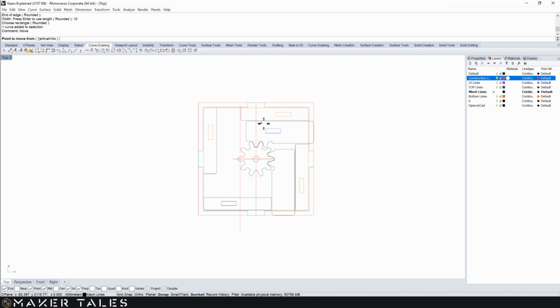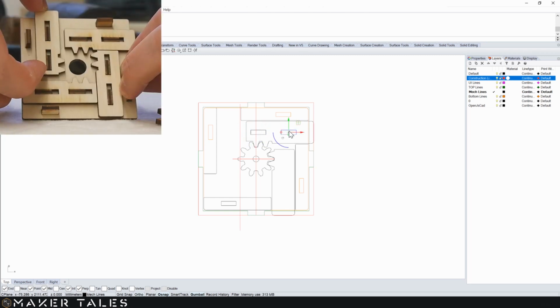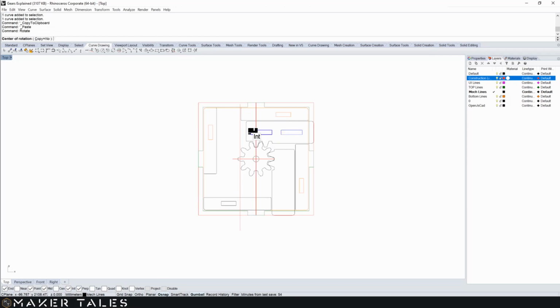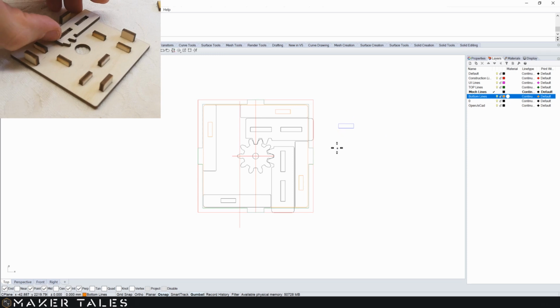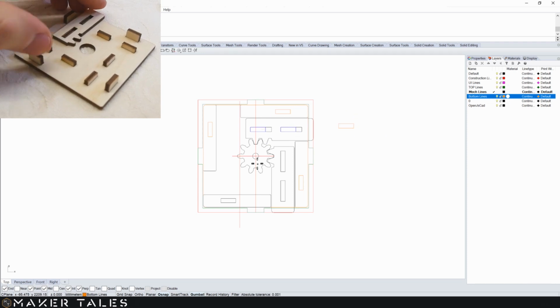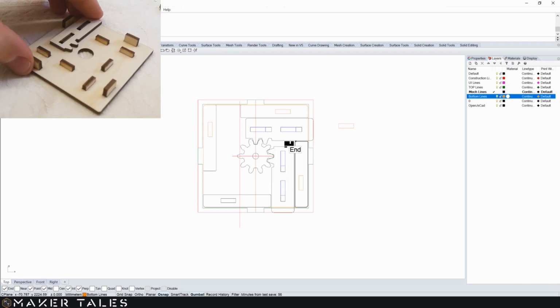To make sure our mech layer works smoothly, we need to either add one long or two short guide rails to each finger. This will make sure that they don't rotate, plus they're going to limit the motion as we have removed the top layer with the pass-through hole. Remember to make these guide rails as long as the full range of motion. Now with the rail guides in place, let's add holes in the bottom layer to add the rail pins.